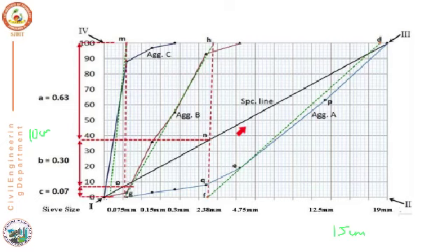After drawing the desired gradation line, we have to mark the percentage and sieve size on the x-axis. If you see here, the 100% passing will be there for 19 mm. 80%, if you look here, is there for the 12.5 mm. Similarly, 55 percentage, somewhere here it will come, will correspond to 4.75. Similar to that, you draw the sieve size corresponding to the percentage passing.